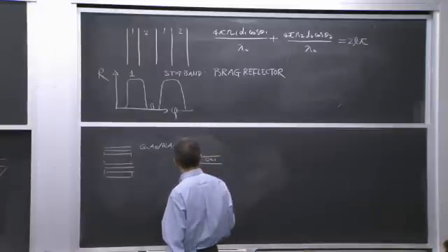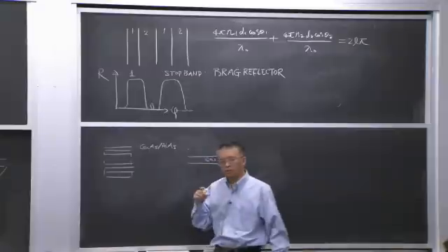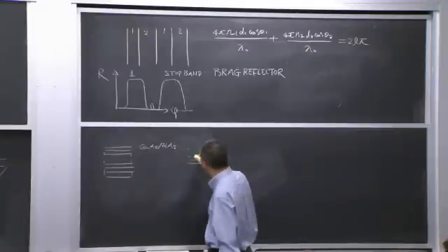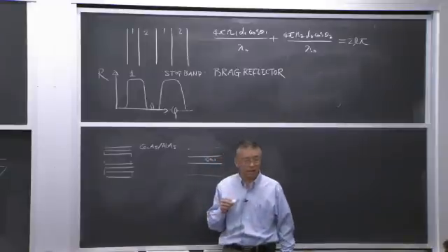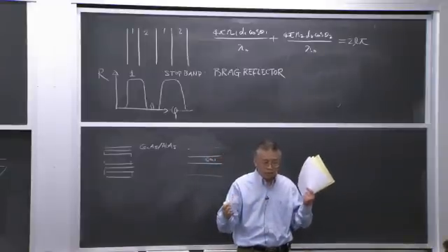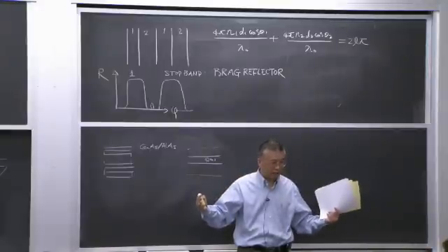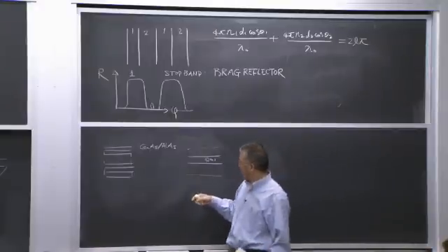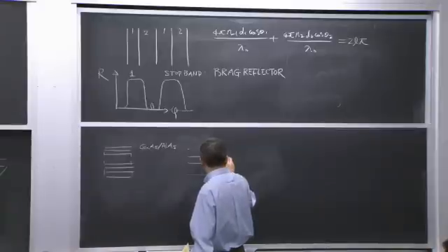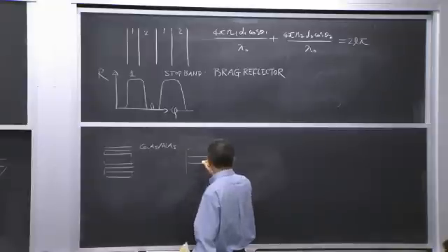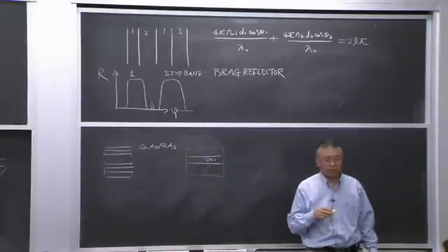We mentioned this configuration before. Quantum well is typically very thin, right? 100 angstrom. So the light will go in a much wider region, so you use total internal reflection. You put the aluminum gallium arsenide in the surrounding, which has a lower refractive index. And in that case, the light is in this region, and they propagate. They come out from the edge of the crystal.